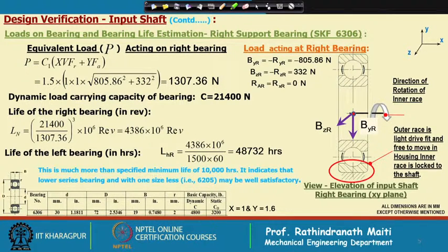Now, if we look into the shaft, we have reduced the shaft size up to 30 millimeter to have the input end of 25 millimeter. But if we go for a 25 millimeter bearing, then probably the shaft input size will be reduced to 22 or 23 millimeter, but that is possible because in between there will be one seal.